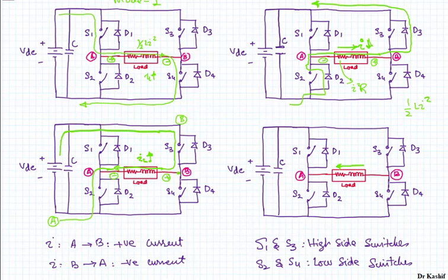So because of that, the inductor will respond, and this point will become negative and this point will become positive, right? And that can be explained in two ways. One way is that your inductor is resisting the change, so the induced voltage across the inductor is given by L di by dt, and according to Lenz's law, the polarity should be opposite with respect to the previous state.